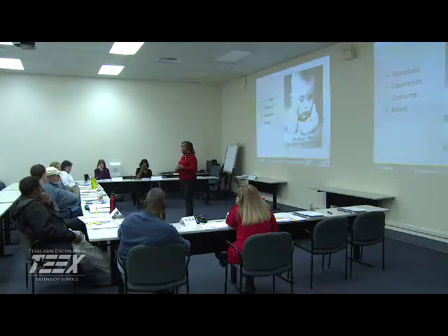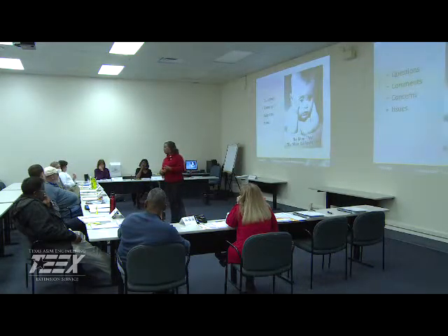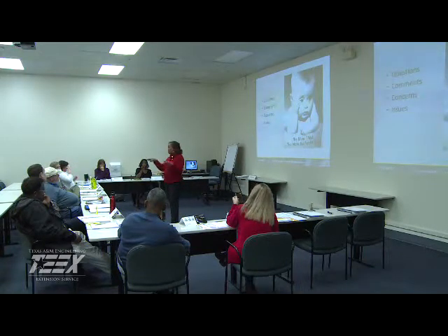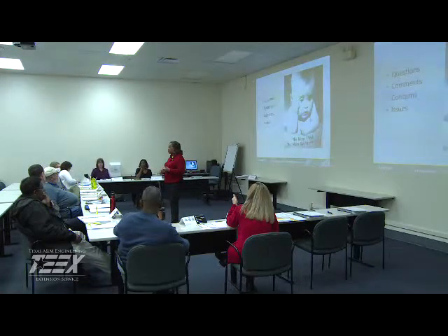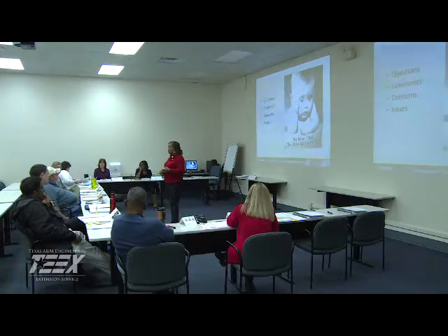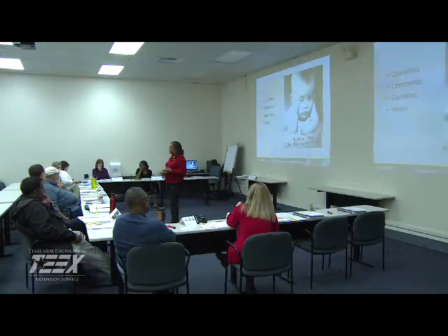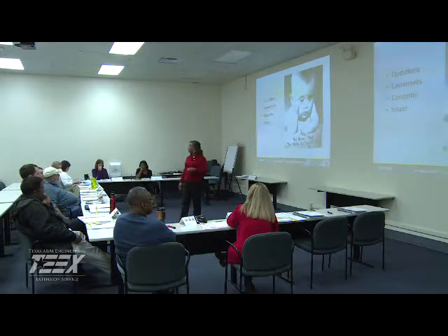Once you do corrosion control, once you install it, you're going to have to keep monitoring it, for pH or whatever. In your own state, you never stop it, you have to demonstrate every day. Right, because if you go out of your set limits, you set a limit for your optimum corrosion control water quality parameters, you optimize them. If they're out of that limit for 9 days out of the month, then they violate. So you can't stop it.